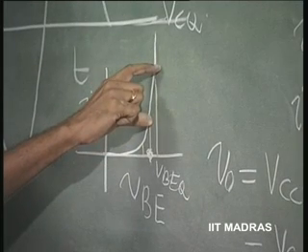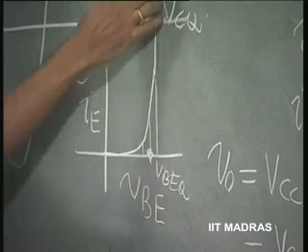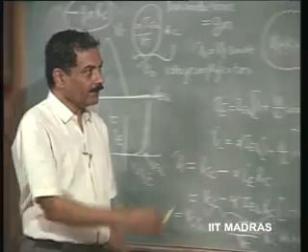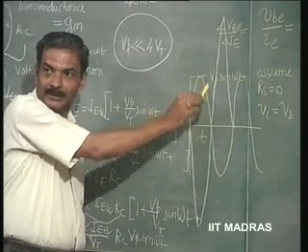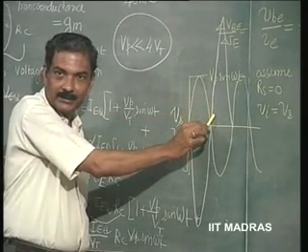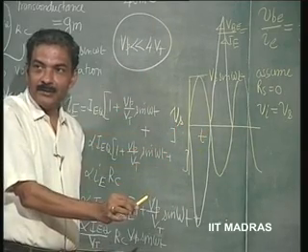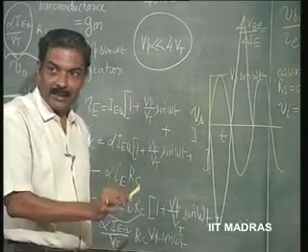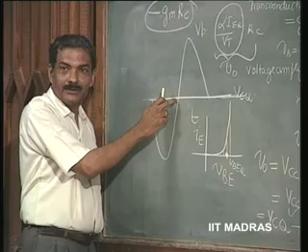The increment in current is higher than the decrement in current because of the exponential relationship, which means that as this signal is applied, the emitter current is increasing here because VB is increasing, but the increment in current is going to be much more than the decrement. If the increment in current occurs, that causes a decrease in voltage.